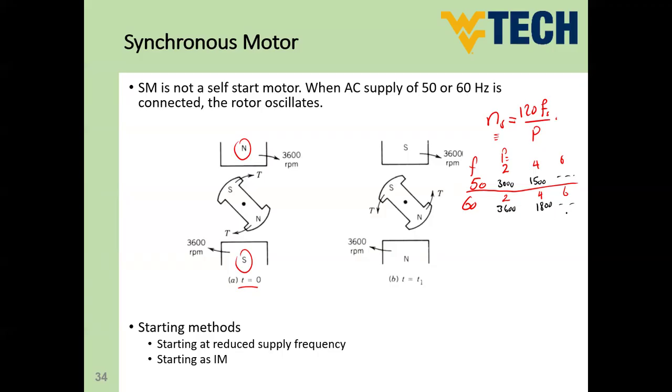So this is the way, guys, how we can calculate the synchronous speed. If the machine is supplied by 60 hertz, we can't have a synchronous speed of, for instance, 2000. It's impossible because the number of poles has to be 2 or 4 or more. There is no fractional pole between 2 and 4. So there is no speed between 3600 and 1800 for the 60 hertz machine.